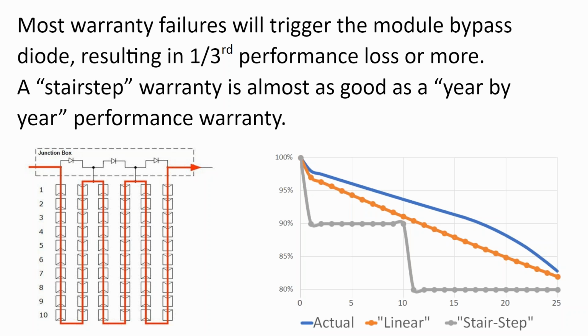And to get the clips installed, we were having to put little temporary toe boards onto the standing seams and then step over them and really reach our arms up to get to the top clip. And for that, putting a hand on the module frame to just get up to where you need is fine, but actually stepping on the module would be catastrophic, even if it doesn't shatter the glass.